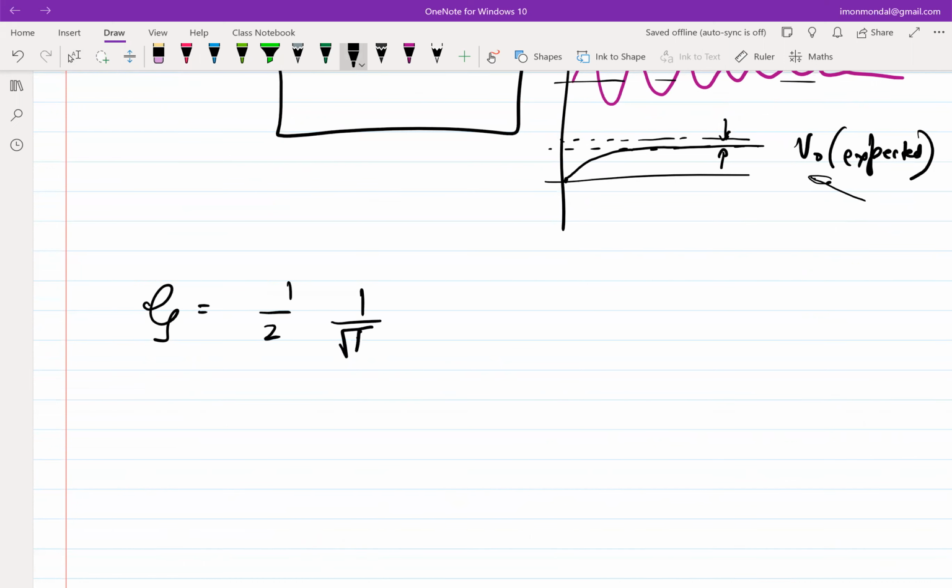But that's not the case, because if the poles are not bunched together but separated, it is possible to still stabilize it under certain conditions for a certain DC gain. And the condition is this. If P2 is even further away, then zeta is more than 1, which means it's going towards the more and more overdamped case.